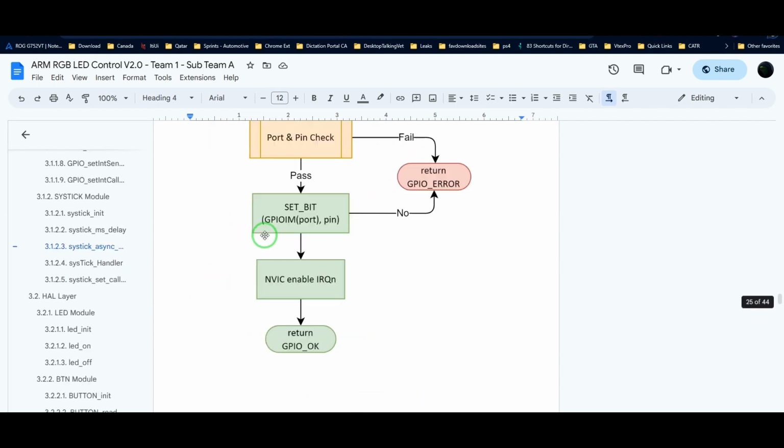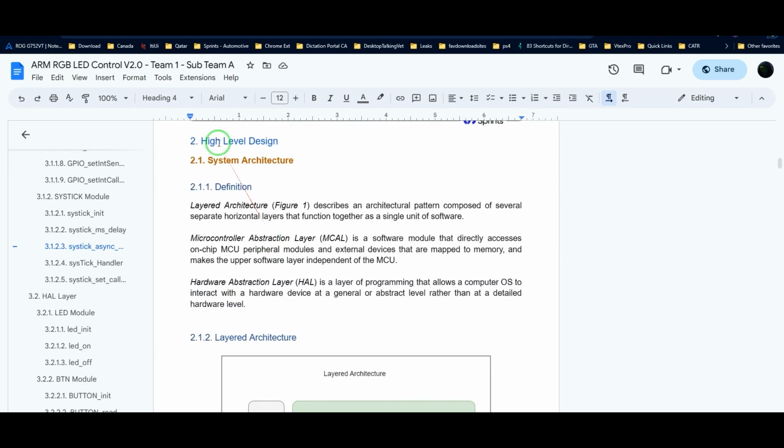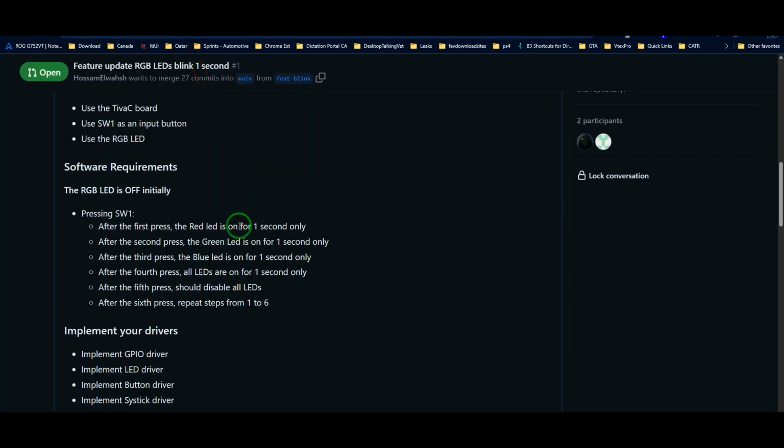The application doesn't need the previous LED to be on if the button was pressed, which will turn on the debounce for 200 milliseconds, and also will cancel any asynchronous 1 second delays.